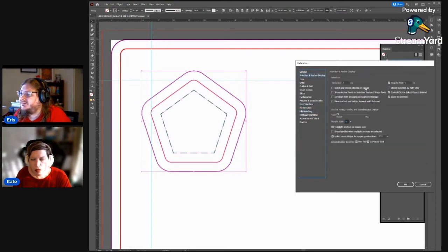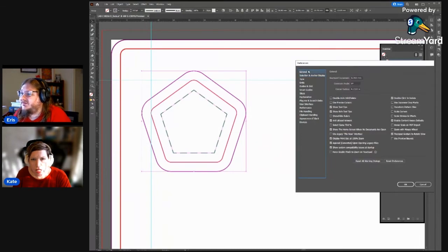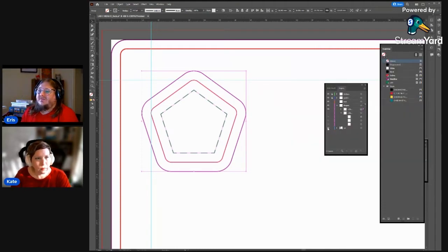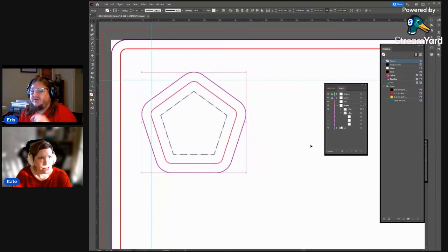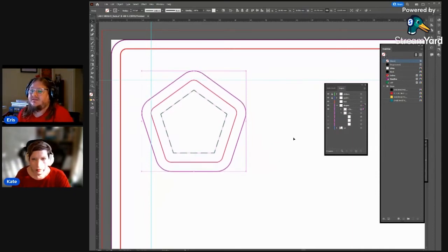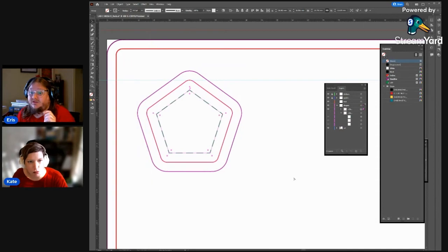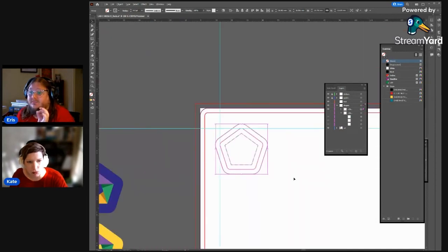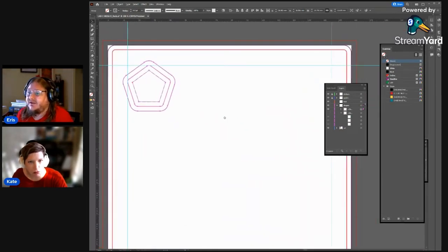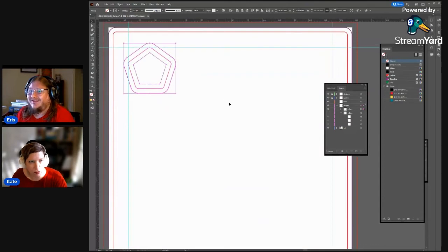Keyboard increment, yeah, there. Let's make it 0.1 of a millimeter. If I'm doing work where I really want that precision, sometimes I'll go like 0.001, tiny amounts that I'm marginally moving things. That's when I'm being my usual very fussy self with my layouts.